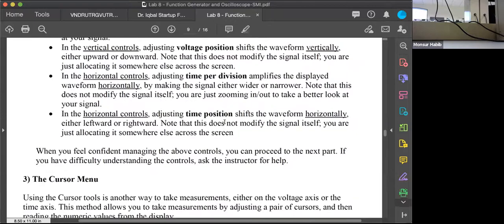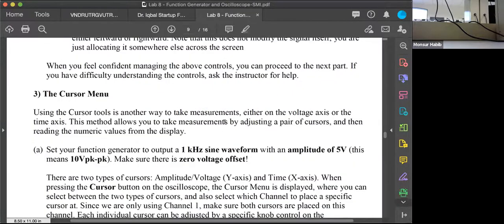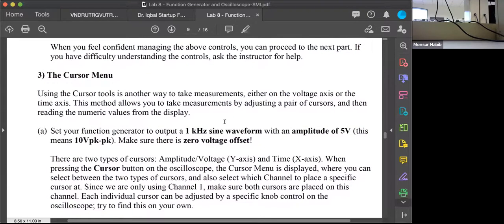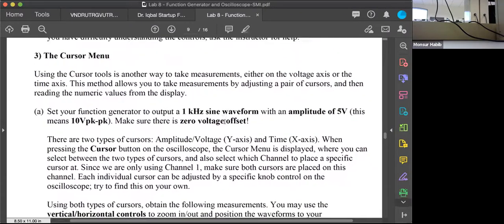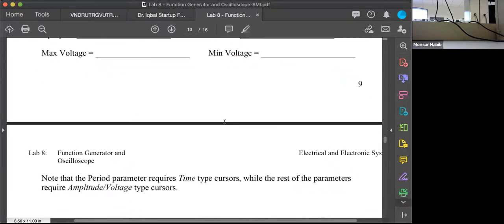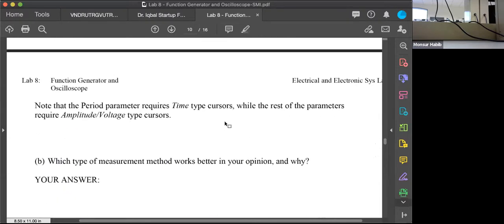Now on the oscilloscope, you can move your cursor to different locations. At every location, you can get the cursor value, or you can use that cursor value to change the display as well. You can pick that place and set the display to make that 0 voltage, and everything else gets adjusted accordingly, up or down. That's again to compare a signal or to see a signal value at a specific voltage. So that's the cursor control and what you can do with your cursor.